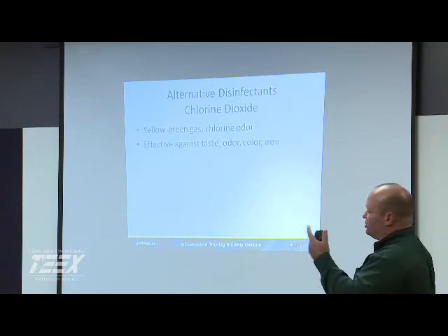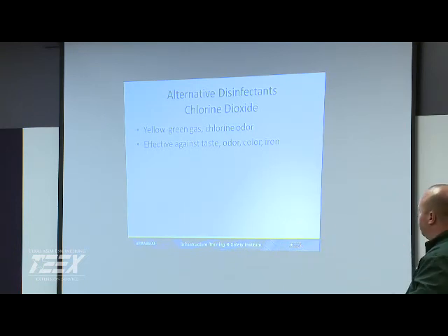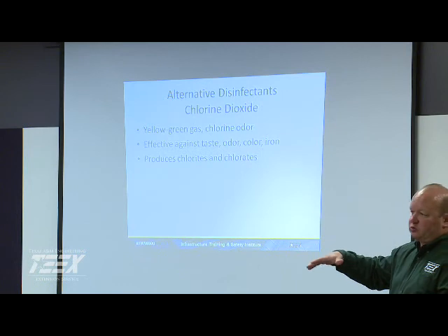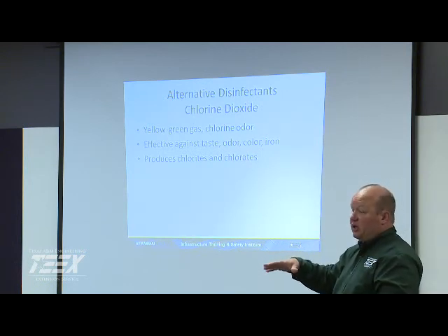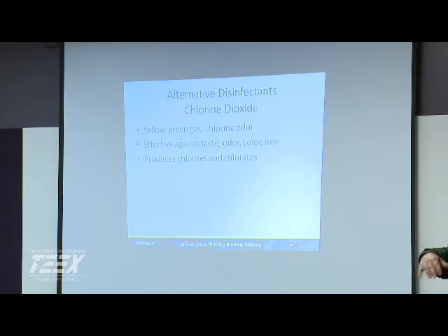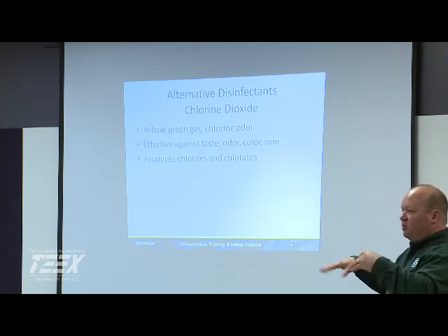Yeah, there's some benefits to the chlorine dioxide, real good disinfectant, taste and odor, things like that. The biggest issue is you got byproducts that are being formed. So you got maximum levels that you really gotta watch. If you exceed them, boy, you got a lot of headaches out in your system. Occasionally you gotta do burnouts in your system, go off your chlorine dioxide, go to chlorine, burn all that out, and then go back.